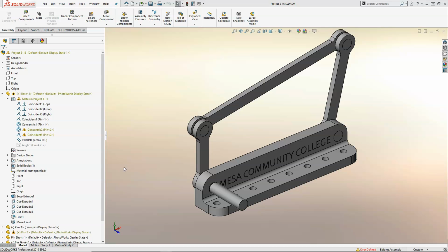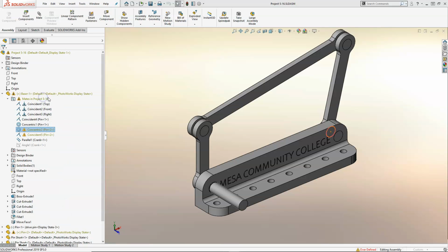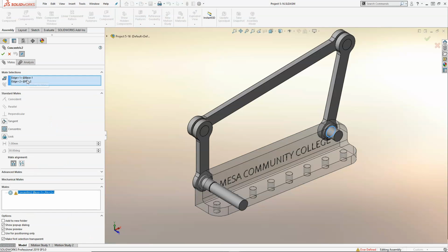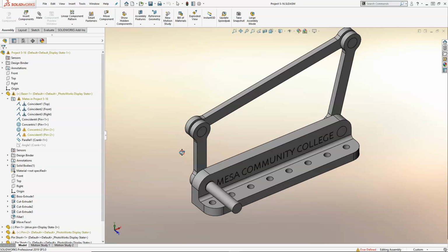Now we're going to work on making our corrections. Since the concentric and the coincident are the two highlighted, let's take a look at what is going on with them. Alright, so I see edge and edge, where on the other side I did concentric and coincident. When that edge gets larger than that edge, they're no longer coincident or concentric. So, what do you want to do?